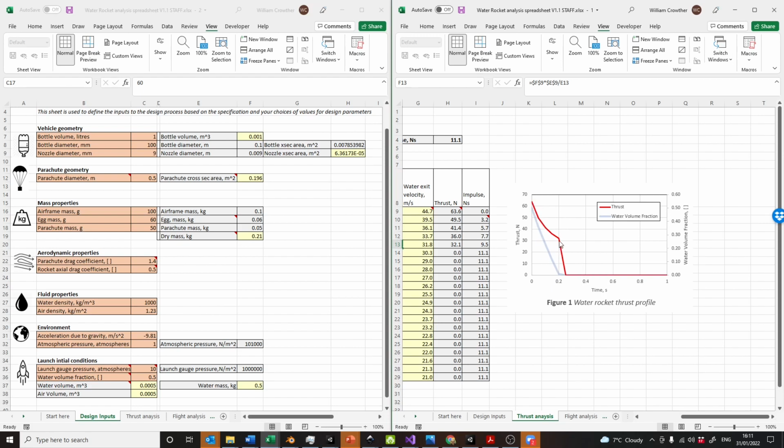What we're really interested in, from a rocket engineer's perspective, is that the area under this curve is the impulse, so that's the total momentum given to the rocket. The boost phase happens pretty quick. In this case, all the thrust is over after about 0.2 seconds, so a fifth of a second, it's all over. But that rocket is then boosted to its launch speed, and the rest of it is just Isaac Newton driving the rocket as it decelerates under gravity and then comes down slowly, hopefully under a parachute. So all the action happens really, really quickly at the beginning of the thrust phase.